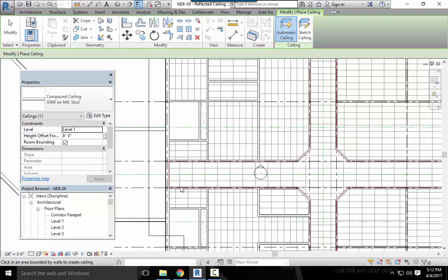Even if you walk into, say, a kitchen area, you'll notice that the ceiling tiles above the food preparation area don't look the same as the ceiling tiles out in the main area. Look at the next time you go to a quick service restaurant, fast food restaurant. You'll notice that the ACT ceiling in the dining room is different than the ACT ceiling above the kitchen. That's because they make them put vinyl coated or non-absorbent ceiling tiles above the kitchen because they don't want the moisture and the grease absorbing into the tile.